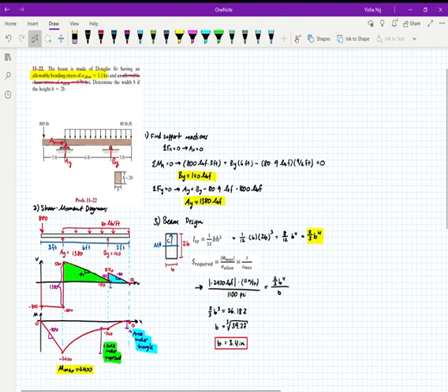At this point, I have another point load. I have 140, so it's going to jump me up to 240. And then from 240, I'm going to decrease again at a rate of negative 80 over the course of 3 feet. That takes me back to 0. So this is another good check. I started at 0, I ended at 0.